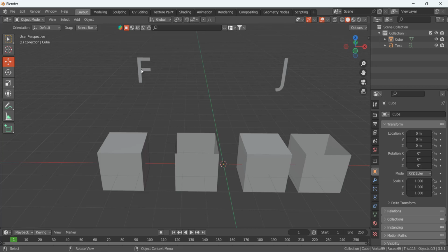So basically the fill tool, we use it to connect two vertices or two edges and connect them with each other. So that's why we use the fill tool, and the same function is for the join tool. It will be used to connect two vertices. But the difference is that when you use the fill tool, you connect two vertices. It will not cut the existing mesh like the face or the edge, but it will just connect between them. And if you selected two vertices, it will add an edge between them. So that's why it will connect them by using the fill tool.